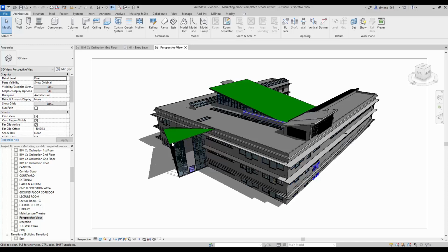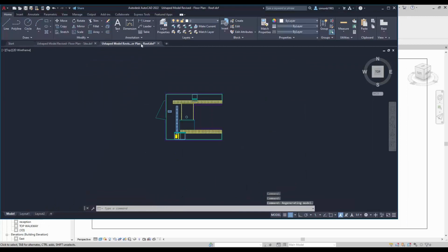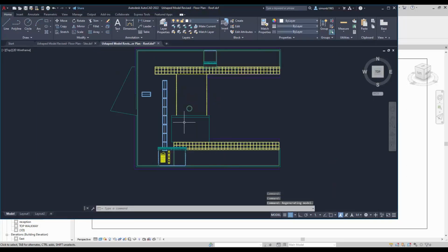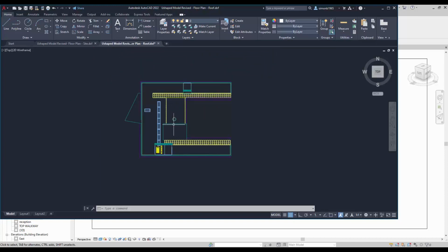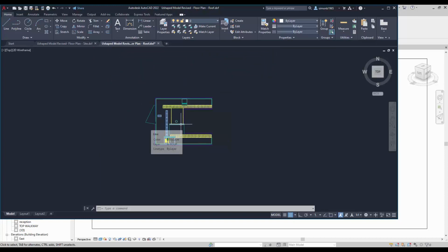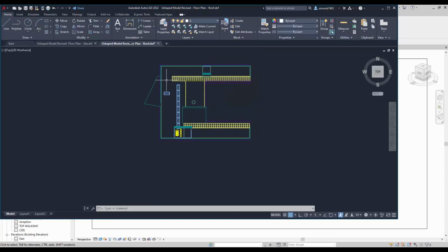Now, Revit may well have a site plan, and exactly the same applies if you're sourcing your drawings from AutoCAD. If, for example, you have the roof space of the layout, what you would effectively do is take a copy of perhaps your roof space drawing. You would then zoom out, and then you would XREF the surrounding site plan so the origin is in the same place. So you'd basically need to move the origin of the site plan to relate to your building that you're doing the analysis on.